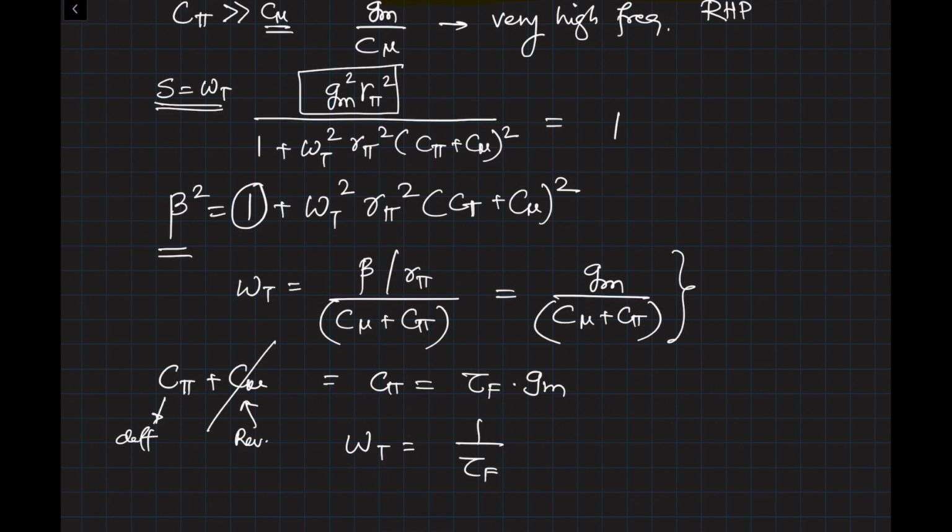In a modern bipolar process, your Ft for the bipolar transistor can be between 200 to 300 gigahertz. Ft is an indicator of frequency beyond which the transistor cannot be used efficiently, because the capacitances within the device will start mattering and dominating your frequency response. So as far as possible, we would like the transistor to behave as ideally as possible and our performance not be limited by the transistor. So this Ft limit gives you that number.